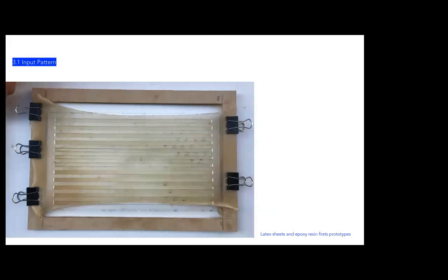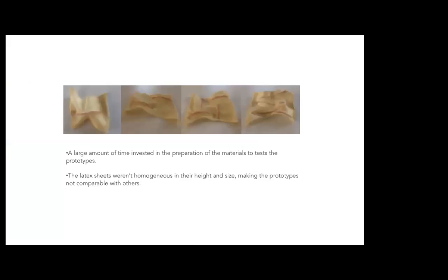The input pattern, as an elastic membrane, is horizontally pre-stretched to distribute force, which creates a volume once it's released. The input pattern is a stiff flat geometry that will work in compression when the tension is released. Through this, the membrane will contract to generate a three-dimensional deformation. First prototypes were done with latex sheets and epoxy resin patterns.